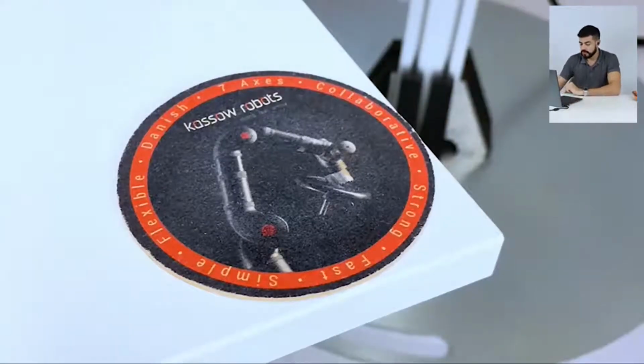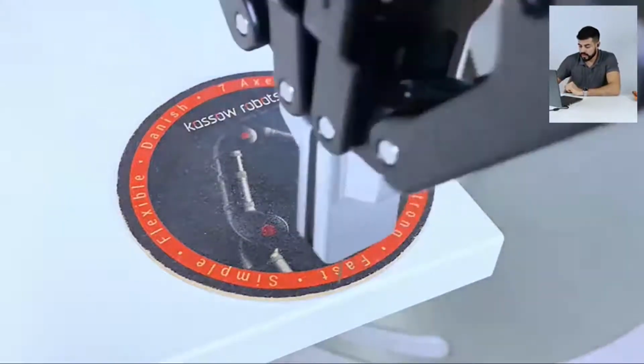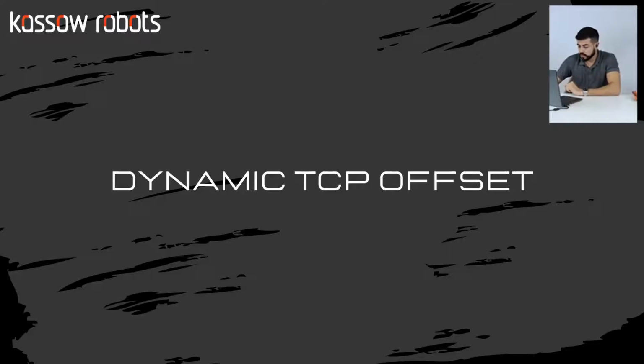Another new feature that's available is the dynamic TCP offset. So with this new feature, it's also possible to update your reference in real time. It means you can include some trigonometric equations, for example, some small range of distance, and adapt the reference of the robot or also the reference of your TCP. So during a trajectory, you can also adapt the position of the robot.